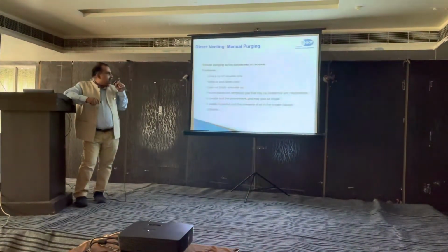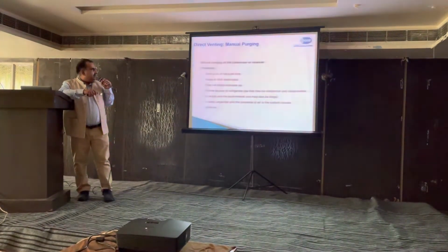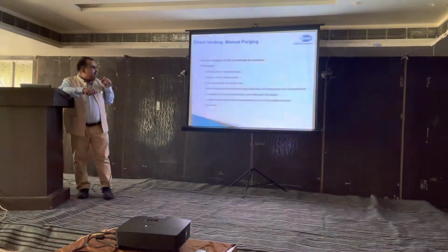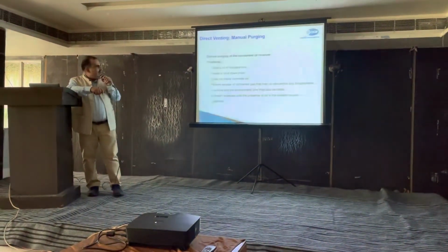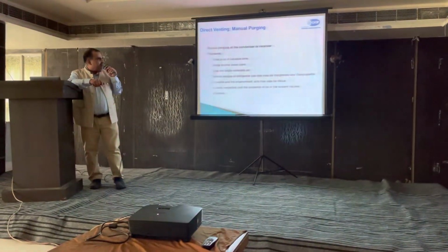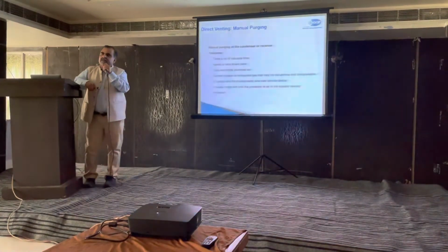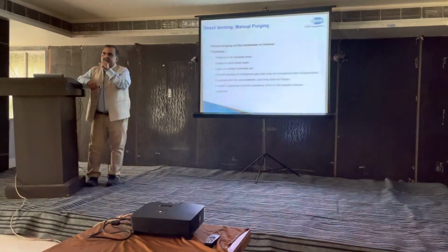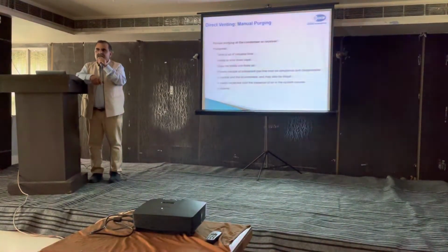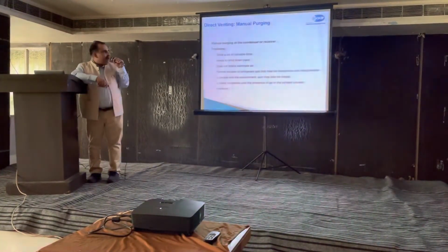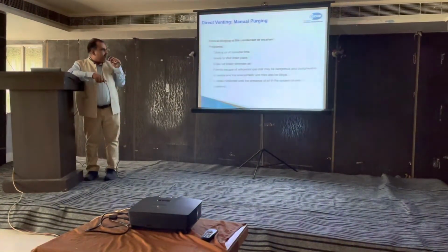As I said, it requires a lot of time because you need to shut down the plant, run the condenser, and then remove the air. And there is no guarantee that it will remove air 100%. The possibility of ammonia leakage is also there, which is very dangerous for the people. Recently we have seen a lot of accidents taking place, particularly in Andhra Pradesh, because of ammonia leaks. Not only in ammonia refrigeration plants, but also in other industries. But ammonia is getting blamed for it. So these things need to be done very carefully.